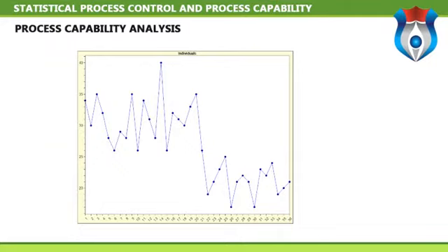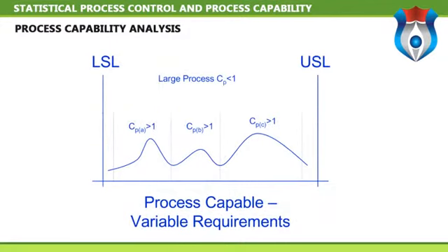Customers, engineers, or managers usually set specifications. Specifications are numerical requirements, goals, aims, or standards. It is important to remember that specifications are not the same as control limits. All methods of capability analysis require that the data is statistically stable with no special causes of variation present. To assess whether the data is statistically stable, a control chart should be completed. Capability analysis is summarized in indices. These indices show a system's ability to meet its numerical requirements.